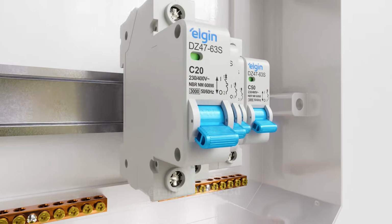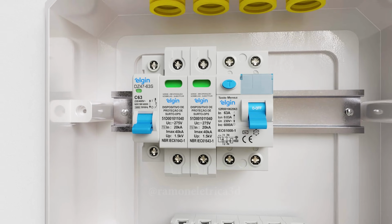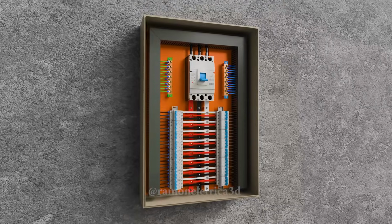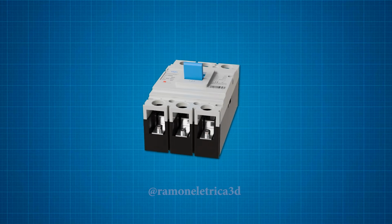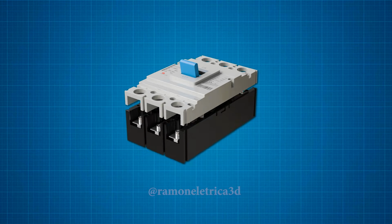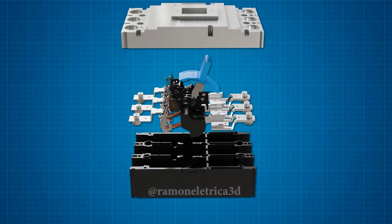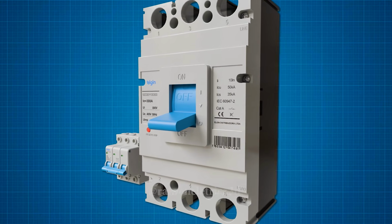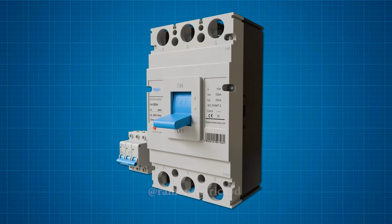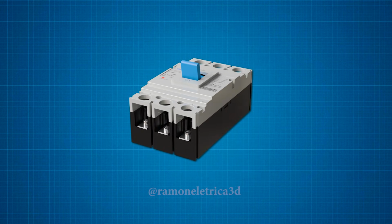Many people are familiar with miniature circuit breakers, MCBs, which we use in residential and commercial distribution panels. But when an installation requires higher currents or needs to withstand larger short circuit levels, that's when the MCCB, molded case circuit breaker, comes into play. In this video, you will understand what an MCCB is, why it has this name, and what the main differences are between it and the miniature circuit breaker, MCB.